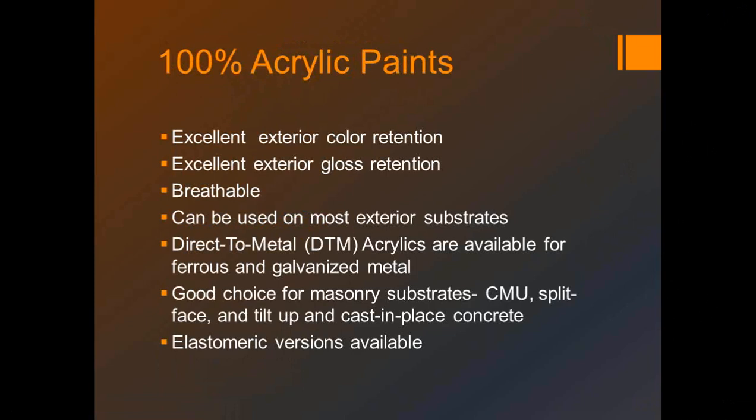Yep. And one of the places I used it was my previous firm had a masonry building that was built in 1871 that had some cementitious parging on the exposed wall that was 4 stories high, and there were no control joints or anything. And so we used the product on that because the building moves a little bit and so forth.